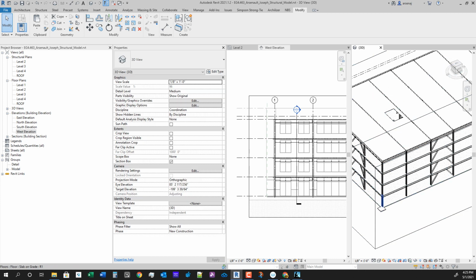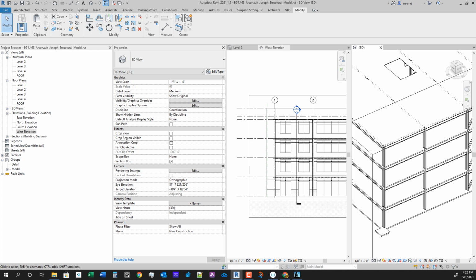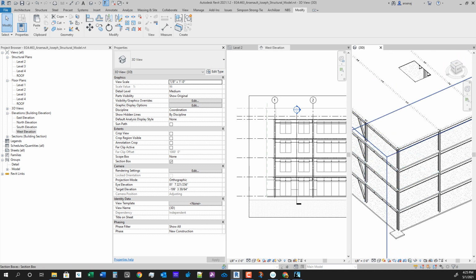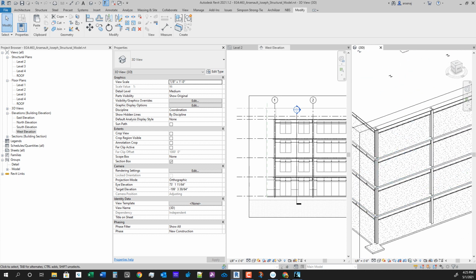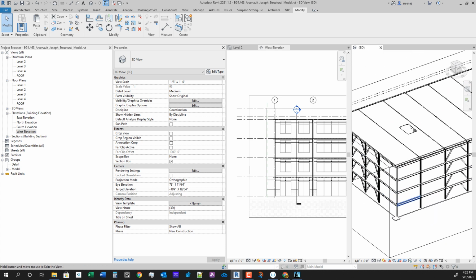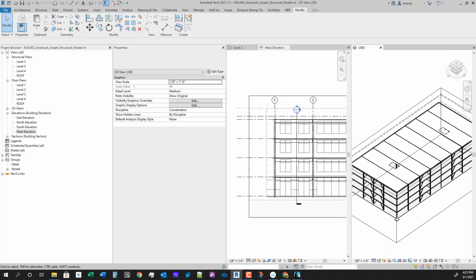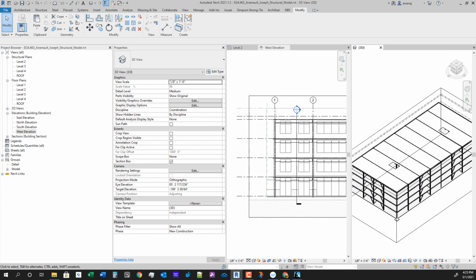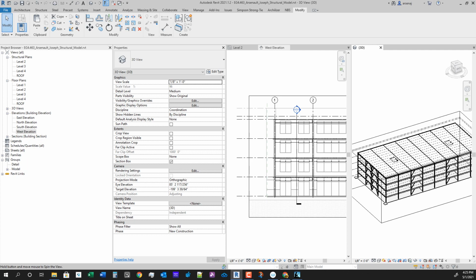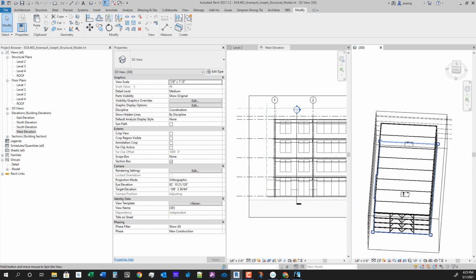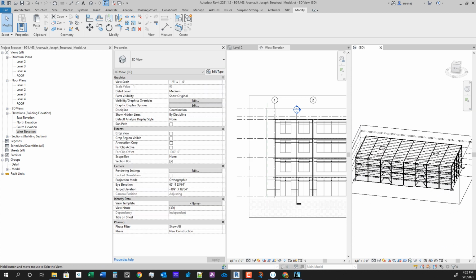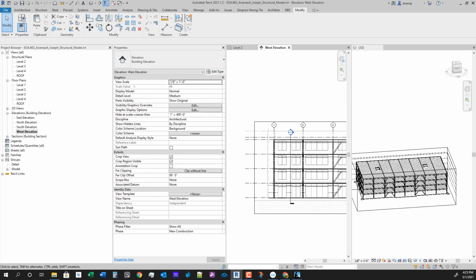And if the architect really wanted these windows here, they might design a moment frame here, which these columns would need to be continuous instead of stopping, and then the connections would be a bit different for these corners. So like we read about, they could use a combination of moment frame, brace frame, and shear walls. So this probably could still fly. An engineer would definitely make it more economical with the beam sizing and whatnot. So let's go ahead and save this.